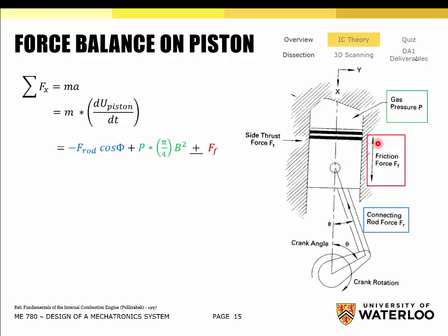So we just talked about where the axial force gets decomposed into a vertical component, which is directly opposing the piston motion, but it's also pushing the piston against the wall of the cylinder. This axial force has a vertical component and a horizontal component. This horizontal component is reacted away in this direction of the cylinder and it's going to wear out the cylinder wall. So just remember that.